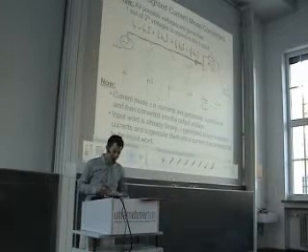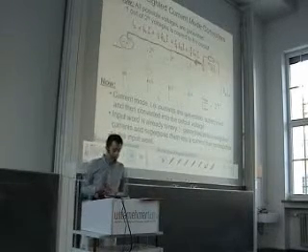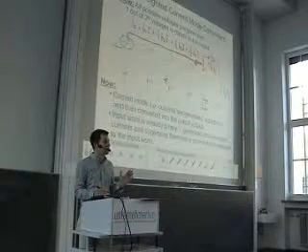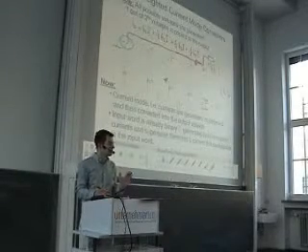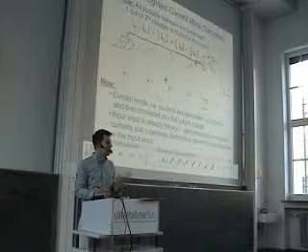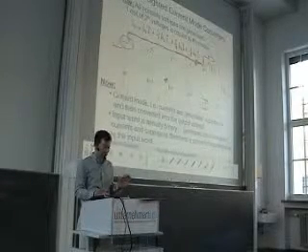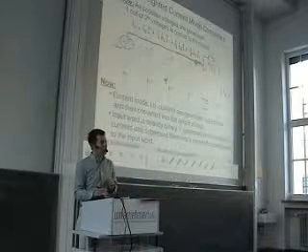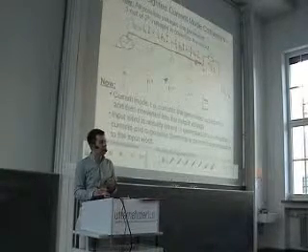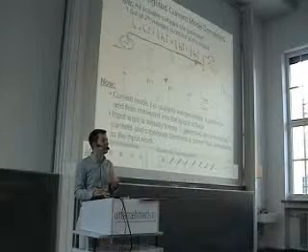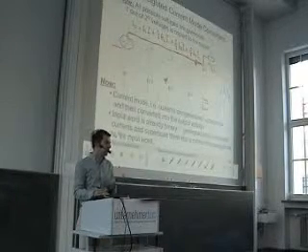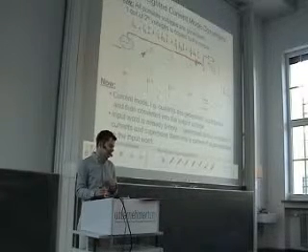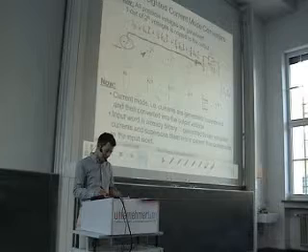However, let me go back to this one again. This means the current in the current sources is always flowing, independent of the switch position. The power is also consumed all the time, independent of the switch position. It is only the question where the current is flowing. So sometimes you can also say this is a current steering technique, because you put the current to one node or the other one.